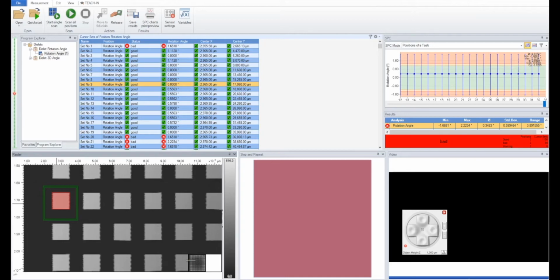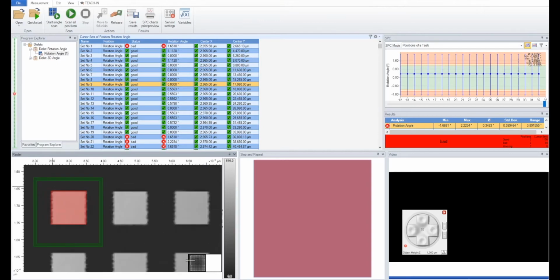The red cursor on the die is the measurement ROI, and the green cursor on the substrate creates the reference plane that the measurement is based off of. This will allow for the results to be relative to the substrate nearest to the individual die, thus eliminating any potential warpage that would affect the analysis. As we can see with this die, there is very little rotation.